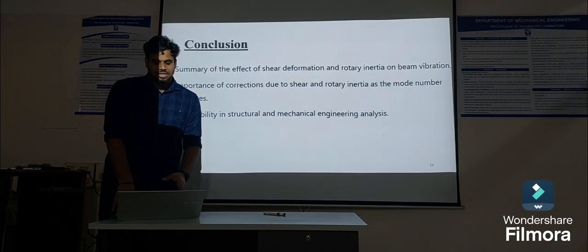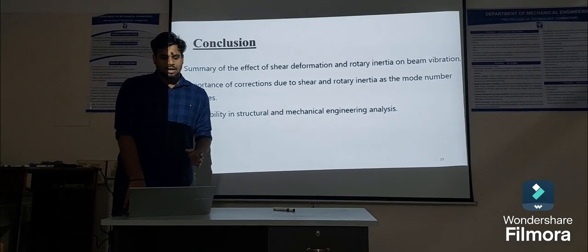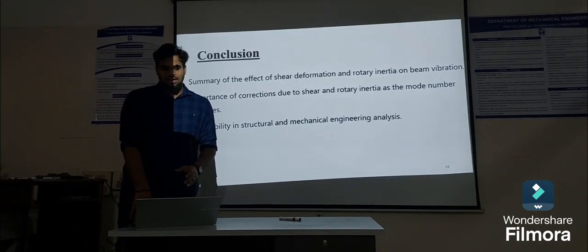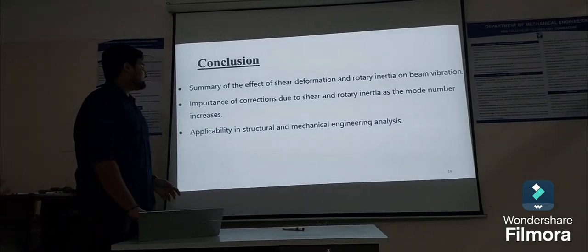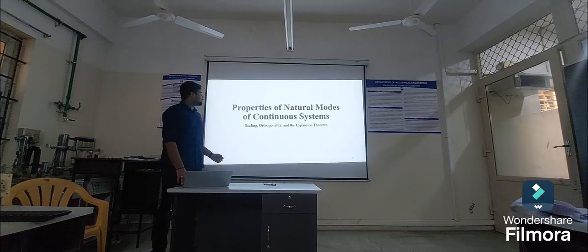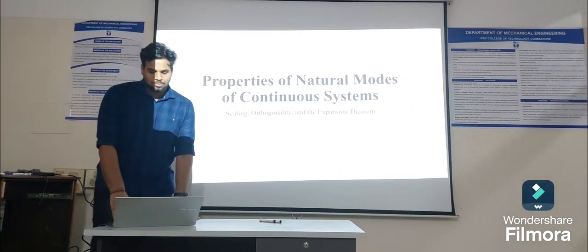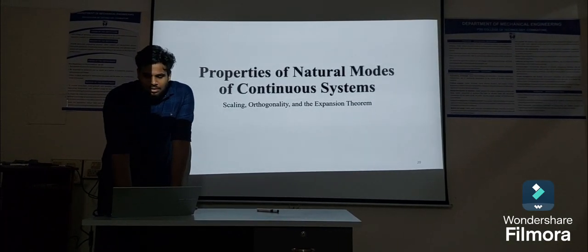Summary of the effect of shear deformation and rotary inertia on beam vibration. The correction due to shear and rotary inertia becomes more important as the mode number increases. It is applicable in structural and mechanical engineering. The properties of modes of a continuous system are scaling, orthogonality, and expansion theorem.